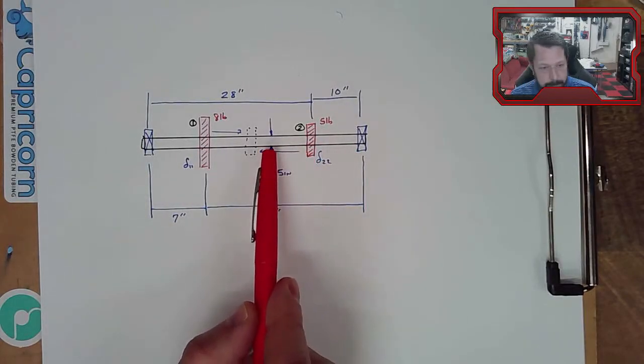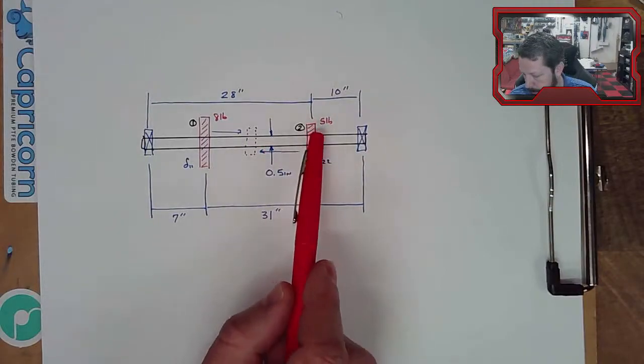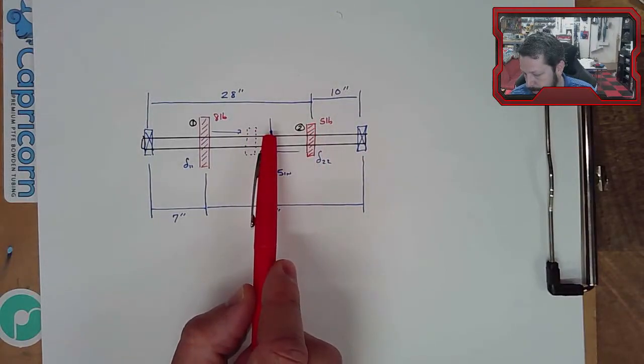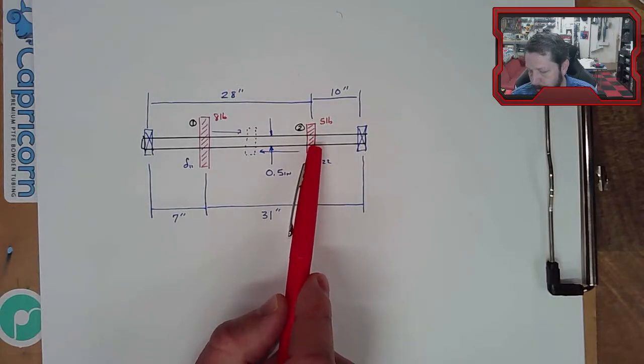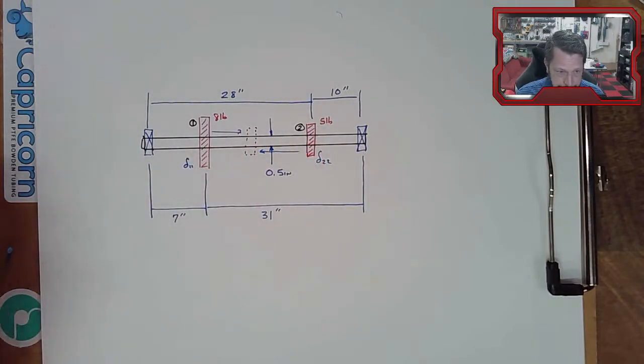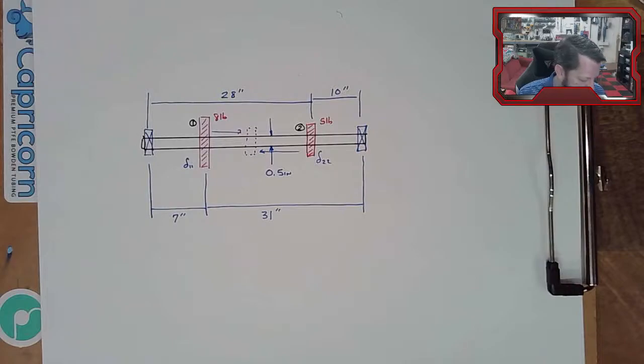So it ends up that we need to put a 3 pound weight at the center to replace the 5 pound weight as far as critical frequency goes. All right. Then we can use our equation 733, but the top part of it.